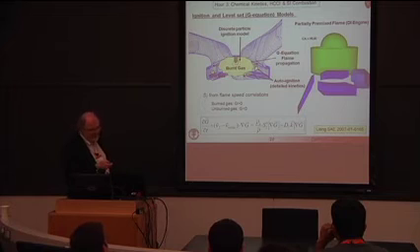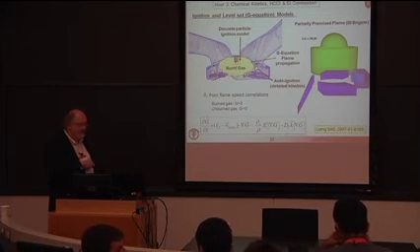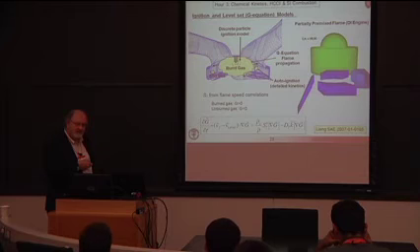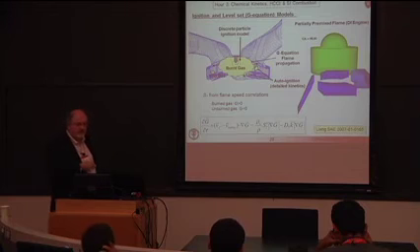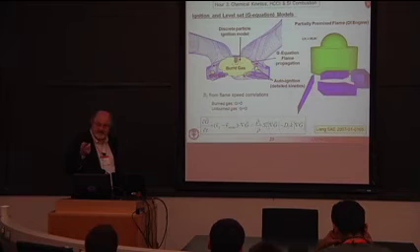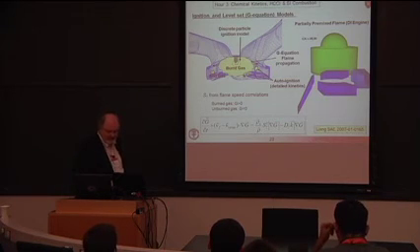So the G equation is shown down here. It's just a transport equation, a time term, a convective term. But on the right-hand side, we have this interesting term. It's driven by the turbulent flame speed. So we're going to need to feed that into this model in order to calculate the propagation of this wave. Things like the gas expansion effect is included here because we include the density in the G model.